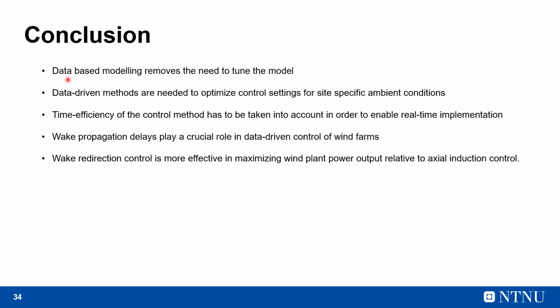Thus, we conclude that data-based modeling removes the need to tune the model. Data-driven methods are needed to optimize control settings for site-specific ambient conditions. Time efficiency of the control method has to be taken into account in order to enable real-time implementation. Wake propagation delays play a crucial role in data-driven control of wind farms, and wake redirection control is more effective in maximizing the wind plant power output relative to axial induction control.